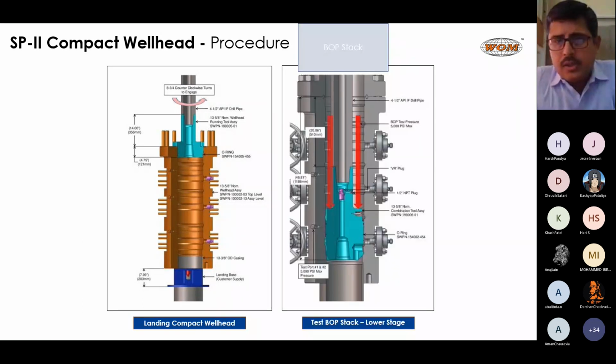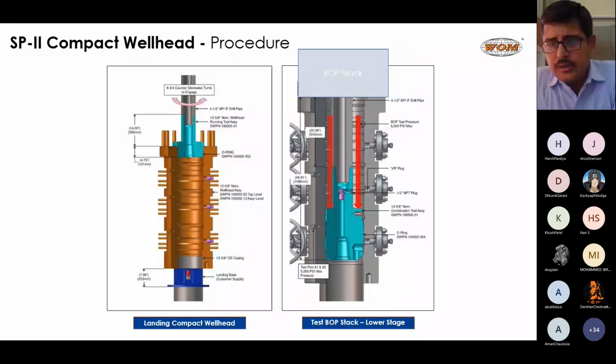I will go ahead with installation of the BOP stack to start the next drilling. Once the BOP stack is installed, I will go ahead with BOP testing, to make sure my BOP connections are perfect, my rams are working, my annular BOP is working. So I do a couple of tests by installing the BOP test plug, which is installed in the wellhead, and all the BOP testing is done against it. So this is the first and the last time I will be installing the BOP. After that, there will be no lifting until the drilling is completed.